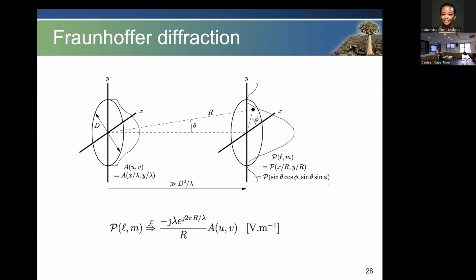Those of you who know diffraction, you normally get these fancy sinc-type functions with side lobes and whatnot. The bottom line is that you go to your physics textbook on diffraction, and you look under Fraunhofer diffraction, and Fraunhofer diffraction defines the relationship between the aperture illumination function and the beam on the sky. That's either the transmission beam or the reception beam. They're both the same.